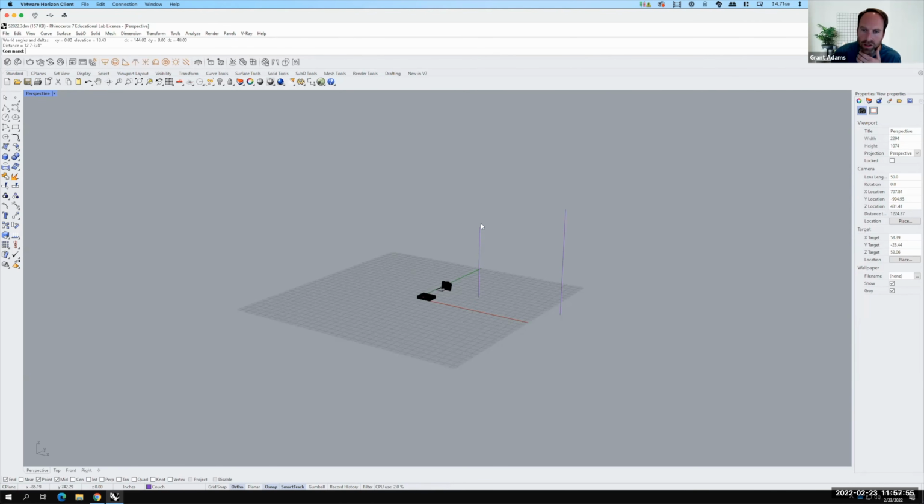It's a special type of curve that forms based on gravity. Rhino has the ability to create catenary curves. So if I type catenary, I can create this. It's going to ask first for the start of the catenary, there. It's going to ask for the end of the catenary, there. And then it's going to ask for the catenary axis direction.